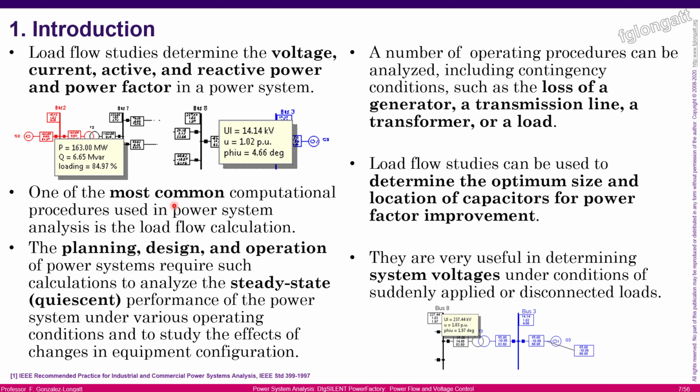There are many power system indicators for the power utilities that require assessment day by day, and many of them are coming from the steady state analysis. For instance, if you want to know what will happen in your system if one transmission line is put out of service, you can run the load flow and see what are the voltages and currents, and see if there is any device that is overloaded.